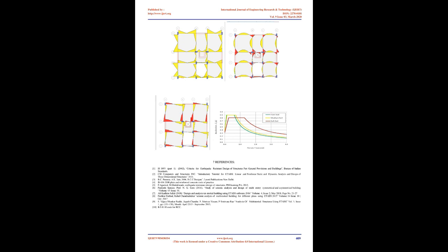From the above tables analysis it is observed that response spectrum modal information and story max/average displacement and story drift values in BS code are higher than values in IS code, T 3.6, 3.7 and 3.8. From the above tables analysis it is observed that story forces values in BS code are higher than values in IS code, T 3.9.